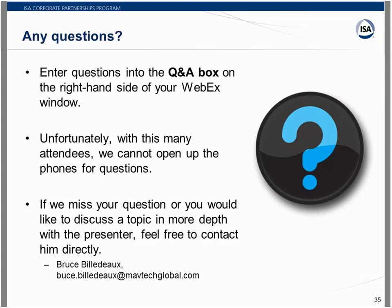You know, I still work on some old Rockwell stuff that's been upgraded to Ethernet. The Ethernet stack is about 3/4 of the memory in the unit, and you hit that with too many requests, it brings down the whole PLC pretty quickly. So penetration tests are difficult because they can disrupt traffic, as you probably already know. I'm not really familiar with one that we would use. It's not our standard right now for Maverick. There are a couple vendors who claim it.